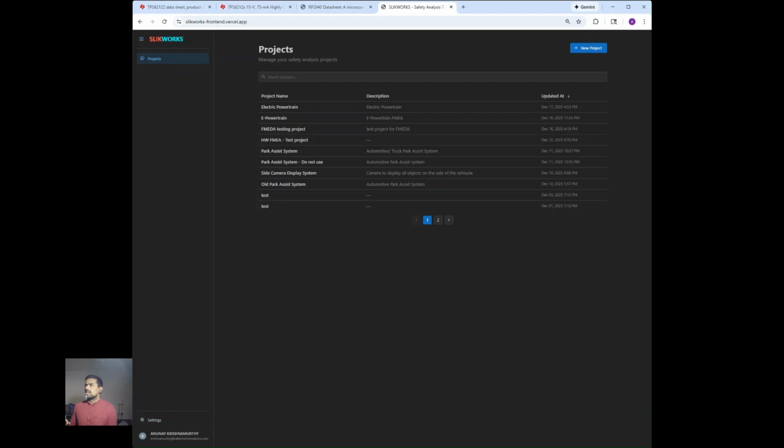And the way this works is you normally would define a vehicle function and you would create a functional architecture for this vehicle function, without allocating it to physical components, just how the function should behave without defining the components that are necessary. And then once this functional architecture is available, an FMEA is performed on this to identify what potential safety mechanisms we need. So this in a nutshell is an FMEA.